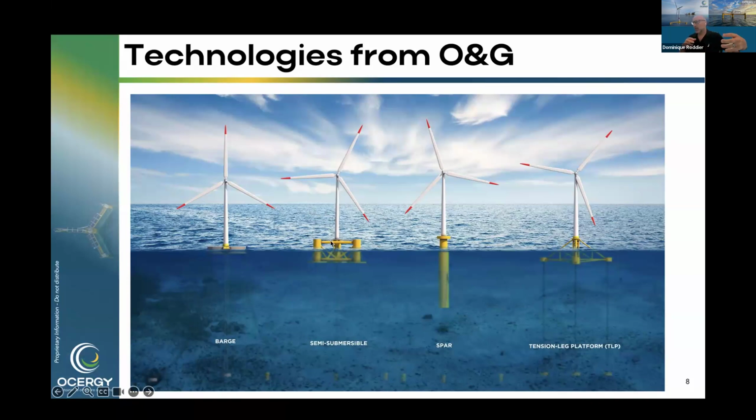Originally, we put the turbine on one side. This was because the cranes couldn't reach the middle, because the turbines were too small, 2 megawatts, like WindFloat 1. This is why we had the ships, because the hull was at quayside and we had to put the turbine on with a small crane. Today, the turbines are so big and so tall that the crane is just as big and tall. So if you do the cosine of the angle, the 35 meters to go to the center is reduced by the cosine of that angle. So the column towers are getting back in the middle, which simplifies everything in terms of hydrodynamics and motions. And further apart means more stable.